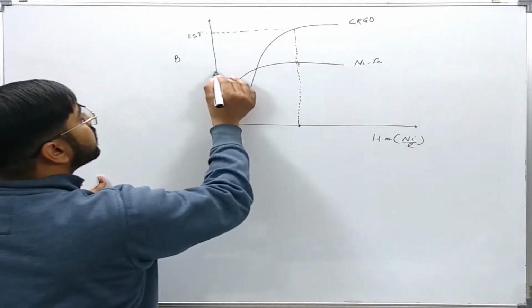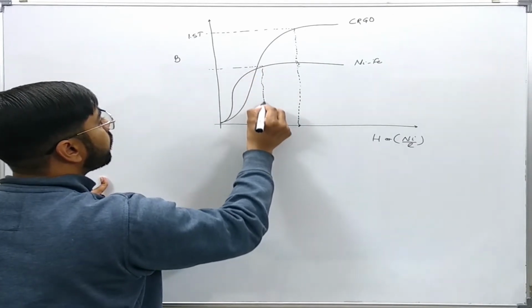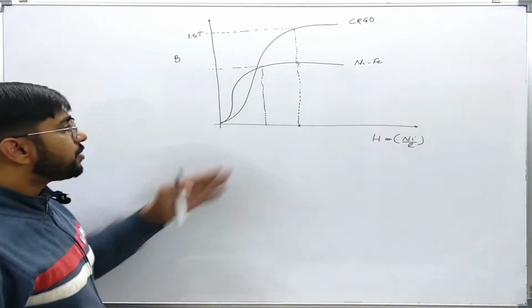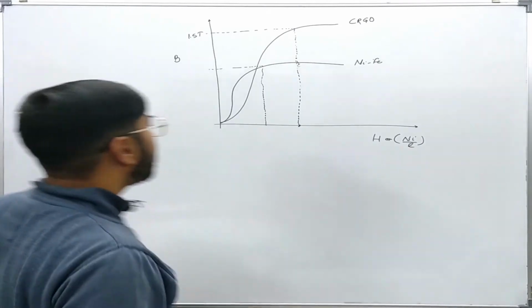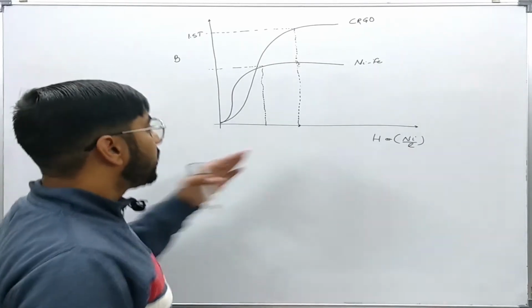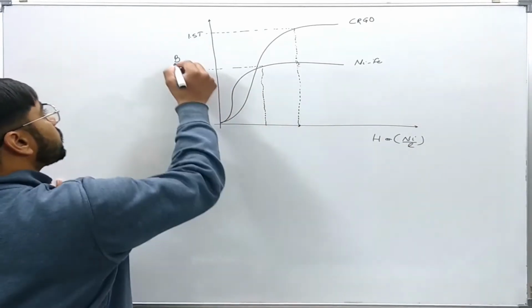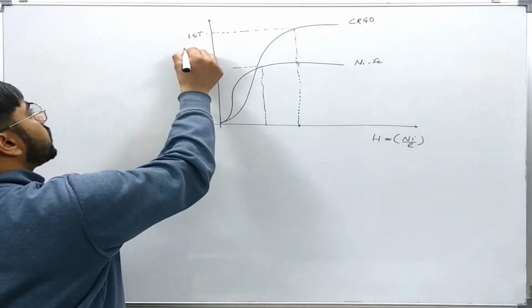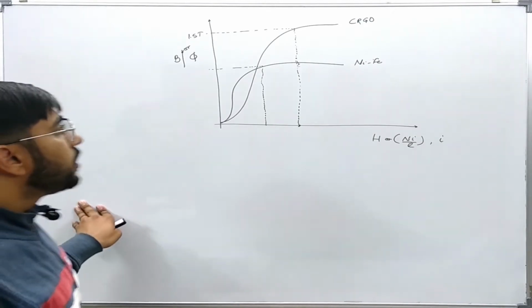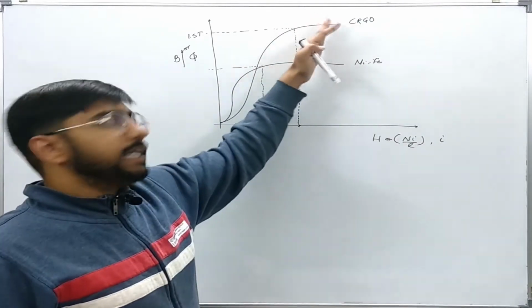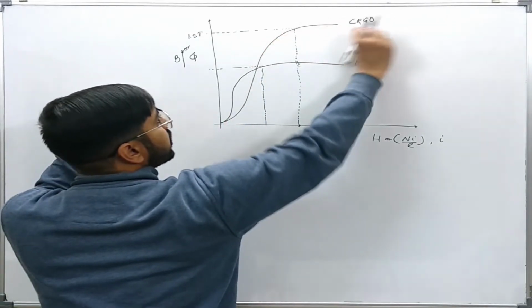However, the CT or the transformer which will be made of this kind of alloy will get saturated at a lower ampere turn per meter or the MMF, or the excitation current. We can also translate it to E and I, or phi or I also.